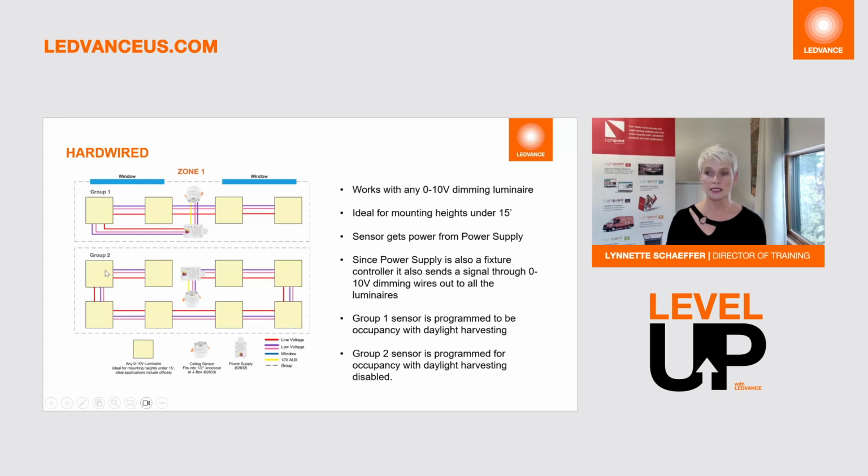You'll notice that in these cases, again, hardwired means that you have that 0 to 10 volt dimming wire that's running from luminaire to luminaire to luminaire. So yes, you do have to run that 0 to 10 volt low voltage control wires in a hardwired type application.